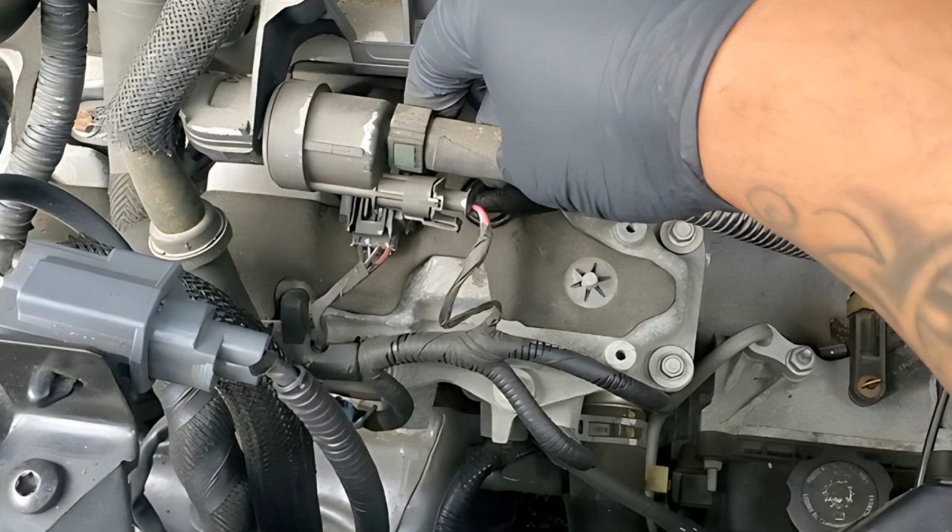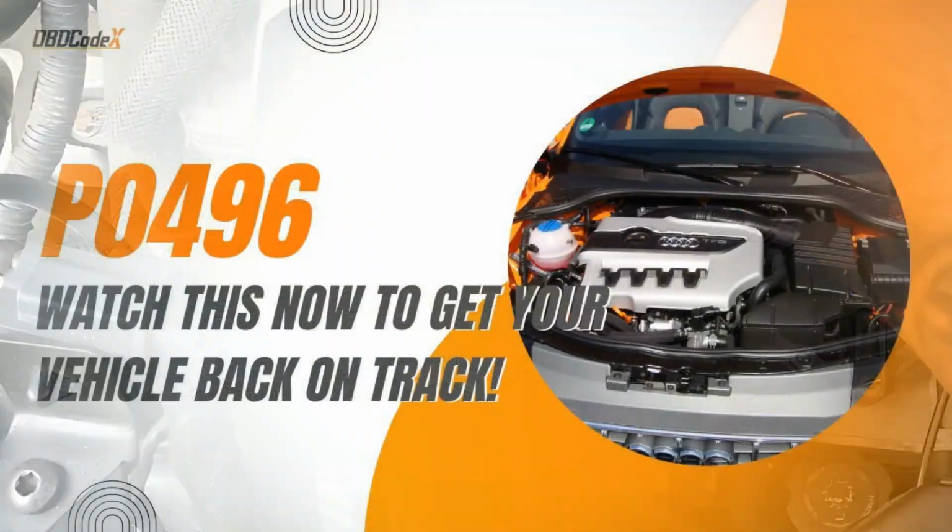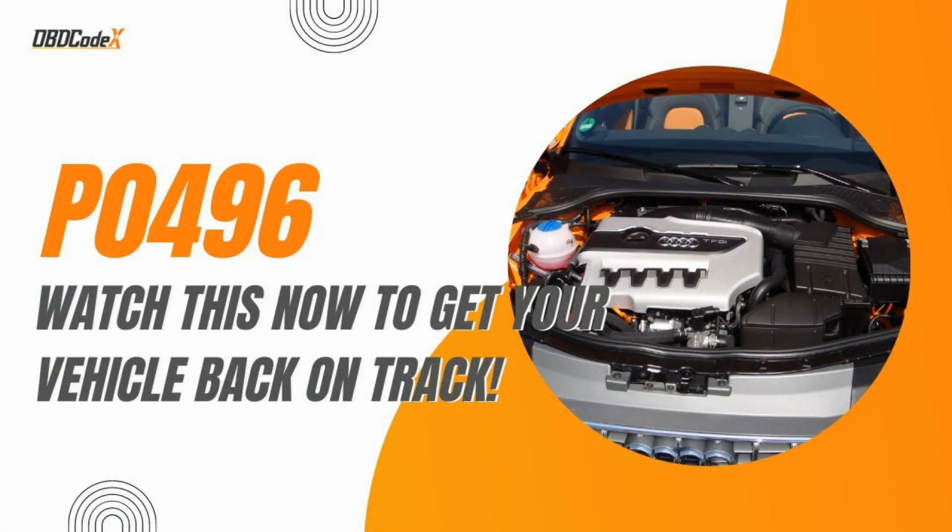Live data monitoring. Use the OBDI scanner to monitor live data while the vehicle is running. Look for anomalies in sensor readings, especially during purge conditions. Fuel tank pressure sensor test. Check the operation of the fuel tank pressure sensor. If faulty, it may need replacing.